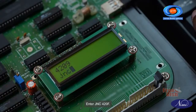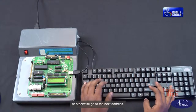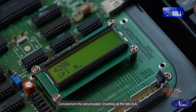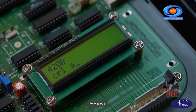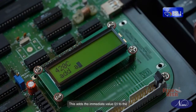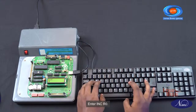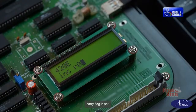Enter JNC 420F. If there is no carry or borrow, jump to this address, or otherwise go to the next address. Enter CPL A. Complement the accumulator, inverting all the bits in A. This operation changes each bit from 1 to 0 and from 0 to 1. Enter ADD A, #01. This adds the immediate value 01 to the accumulator A. Enter INC R0. This increments the register R0 by 1 when the carry flag is set.